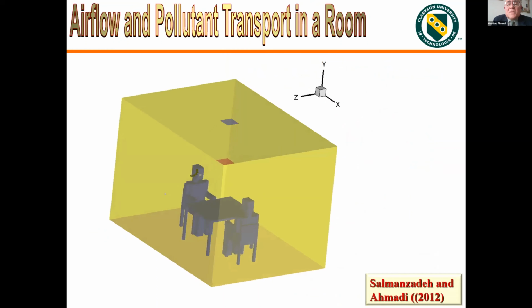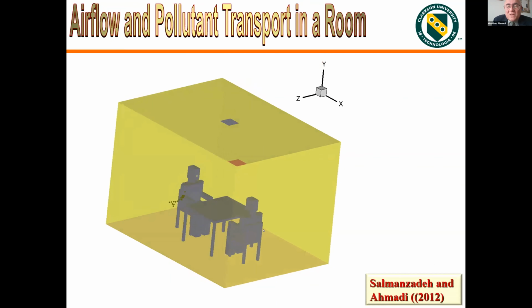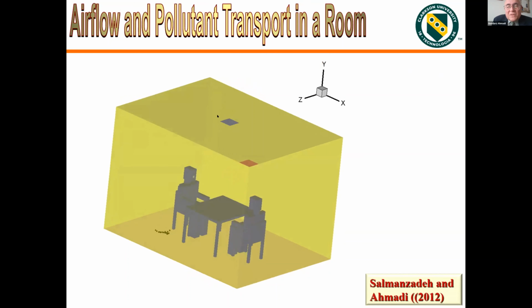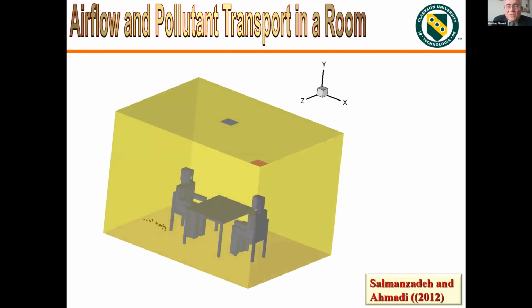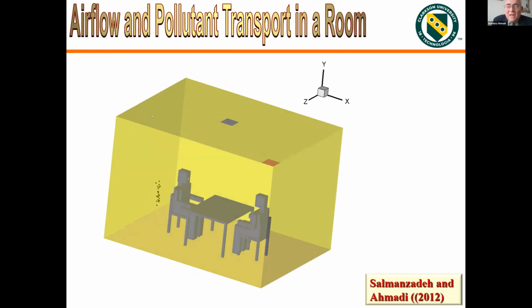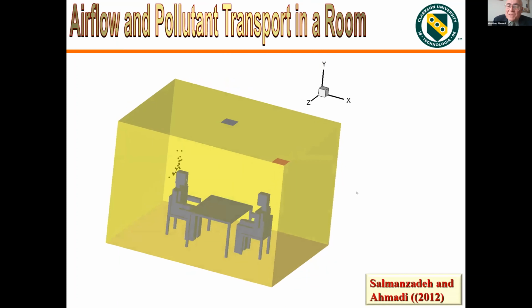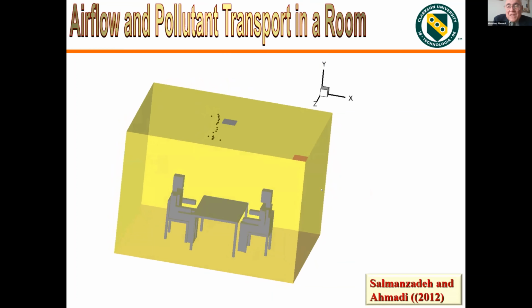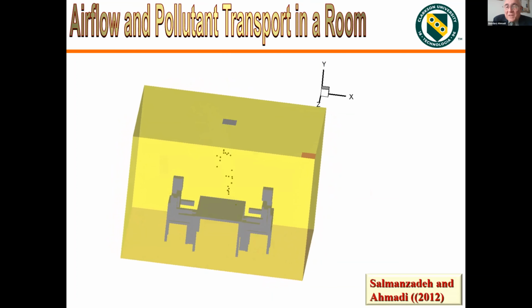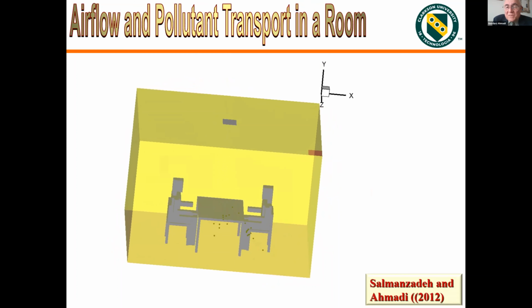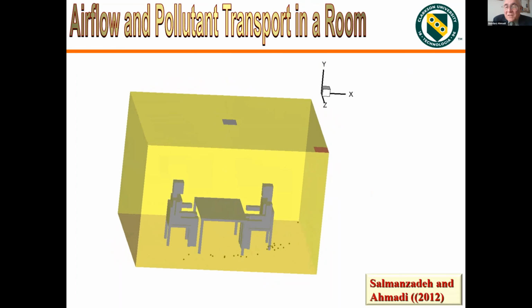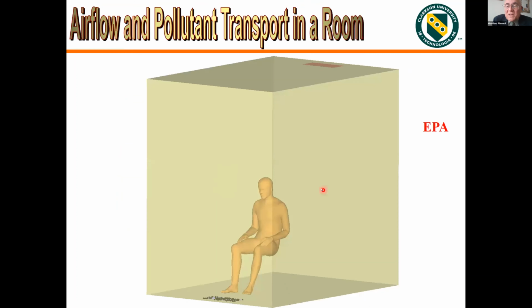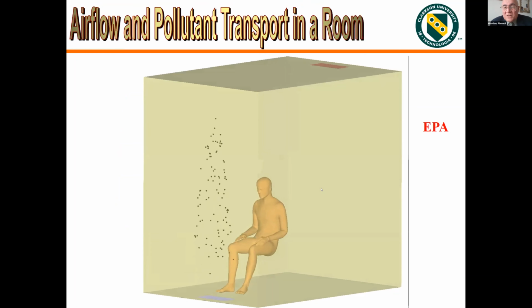These are some simple simulations. We are looking at 2 people sitting at a desk in a room, and there's an air conditioning system. One person coughs and releases some particles, and we look at how they get captured or breathed in by the next person. That's relevant to see the chance of exposure of the people. Indoors, certainly the aerosol chance is much higher because the particle concentration is higher, and they have to be cleaned by the air conditioning system.